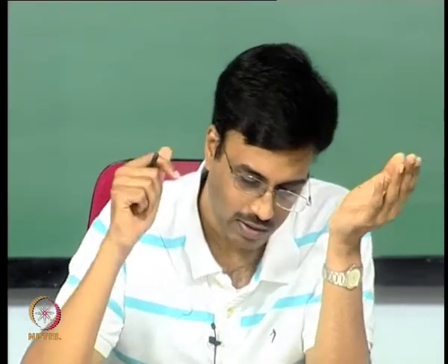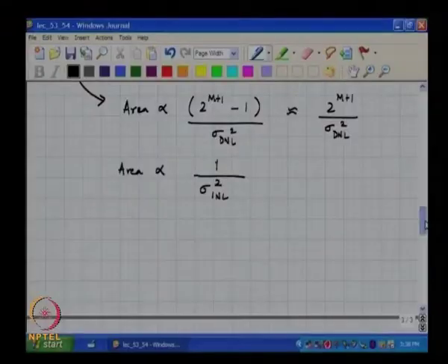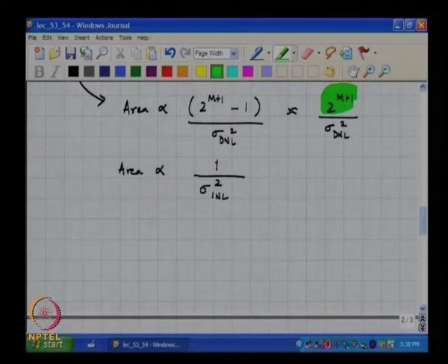No, because the area of the decoder increases when there is more and more thermometer. Correct. Whereas when you increase the binary portion, the area of the current sources themselves are increasing. Yeah, so that is quite right. We believe that there will be a sweet spot, because if we choose a completely binary architecture, the area of the current sources becomes very large, right, because as we just saw, the area of the unit element is proportional to 2 to the m plus 1, all right.